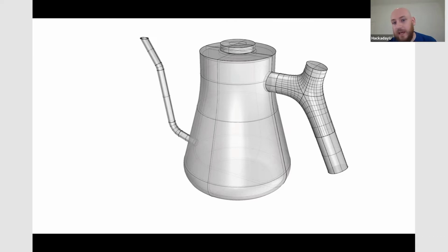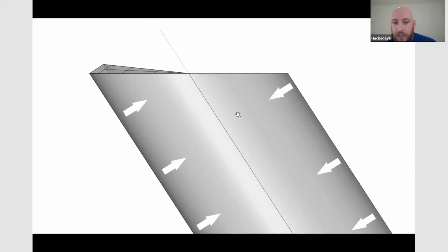And then I can offset surfaces, which makes them solid and gives them a thickness. If I wanted to 3D print the object, they would want to have a thickness because, as I mentioned in week 1, surfaces and curves in Rhino have a thickness of 0, so they have no thickness unless they are a closed shape or a closed poly surface. So now I've offset a thickness, and I've done this deliberately in the wrong order because now I have this problem at the top of the spout.